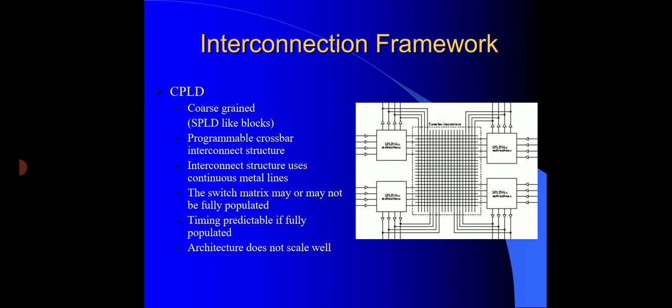Next is the flash programming technology. Flash programming technology has two advantages as well as a disadvantage. It is more efficient, but it does not allow reprogramming an infinite number of times. Also, antifuse programming technologies are mainly used in low area designs, with low on-resistance, but the parasitic capacitance is very high, and it is non-volatile.